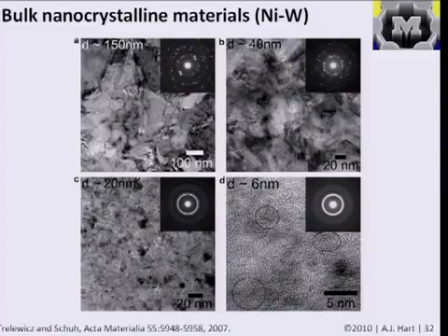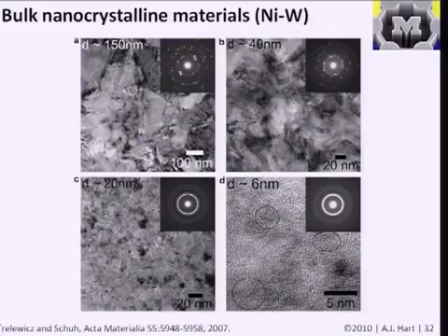So I like to think there are two perspectives on engineering the mechanical properties of materials by nanostructuring. In the first part, we've talked about how materials are individual bonds and how that inspiration can help us explain the differences in the measured mechanical properties of nanostructures versus macrostructures, and how stiffness might be close, but strength might be different. Another means of engineering materials to control their mechanical properties is a top-down approach, where you adjust the grain structure of materials.